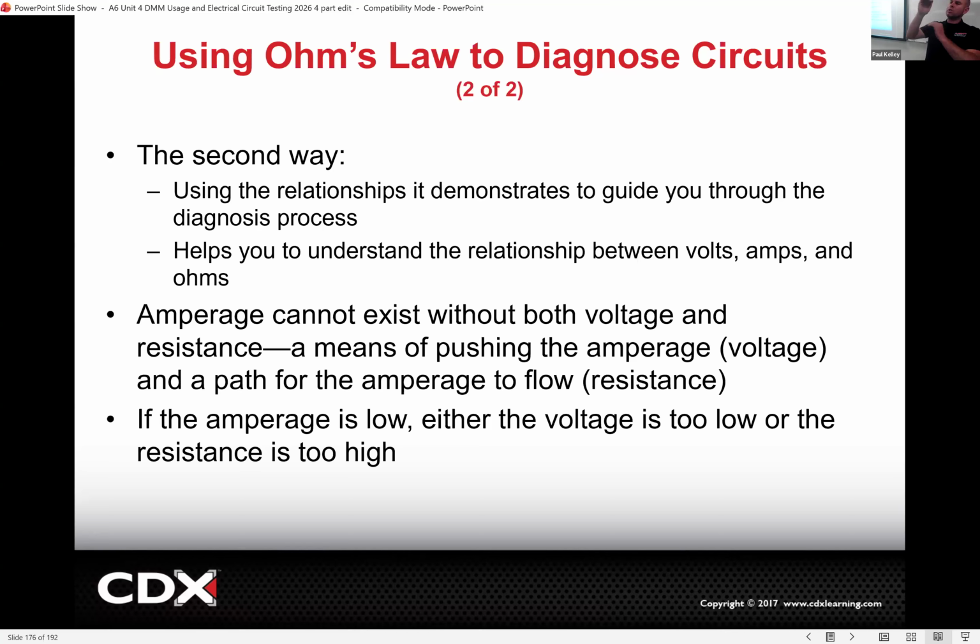So if you have excessive voltage dropping across the switch, you know it has excessive internal resistance. You already know kind of what you got. Like, yes, the switch is bad. I agree. But specifically, how I'd write that up more legally is excessive voltage drop, which is associated with this excessive resistance. If you want to double check yourself, go ahead and measure the resistance. But sometimes your resistance measurement with your little meter and your little 9-volt battery, it might not show that much resistance, but when you put a lot of amps through the circuit, you can measure the resistance more effectively through a voltage calculation. Cool, so that's good.